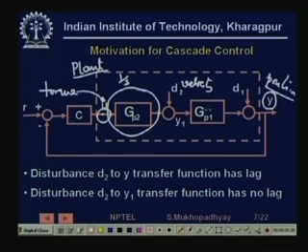Again between velocity and position you have another integration. So this is another 1 by s, and you get position. So you see that between input torque and output position you have two different subsystems. In the case of a motor, it is an integral. So this is a very typical situation.